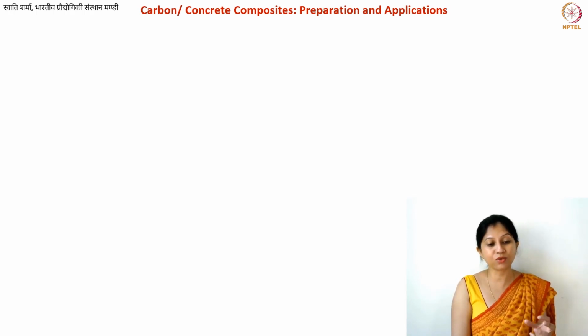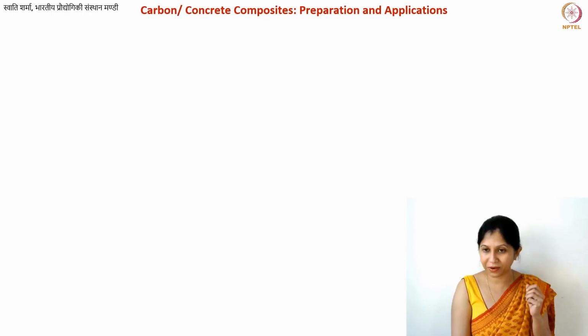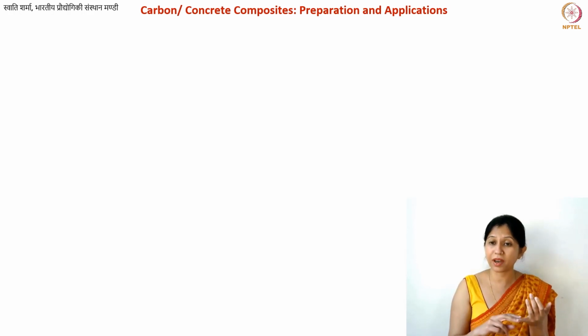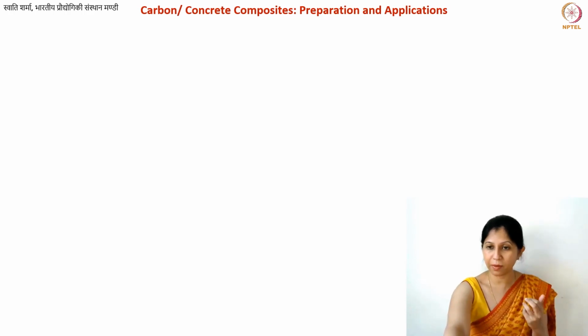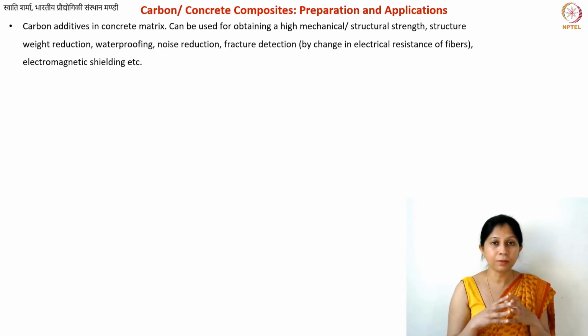However, sometimes you just want to make your concrete stronger. And for that, what you need is filling of the pores of the concrete. That can be done using carbon nanomaterials. So in this particular case, we are also using carbon particles, although very small, nanoscale particles, or graphene, or even carbon nanotubes. So for reinforcement of concrete, you can use carbon nanomaterials. However, fibers still happen to be the first choice for giving the structural strength. We will see how.